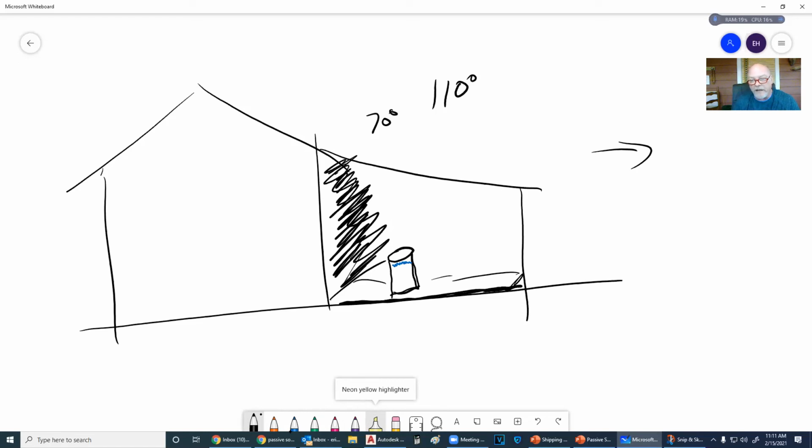So one of the things, in passive solar, it is equally important to have passive cooling. All right, so you've got to have this, especially in our climate, we've got to go both ways. So one thing that we did here is we removed the water in these things and we put sand in it and then poured water back into it. So what happened was we ended up with an evaporative system in here.